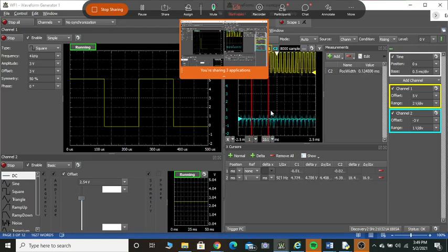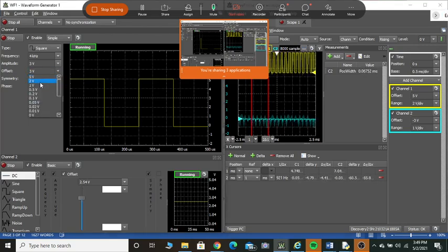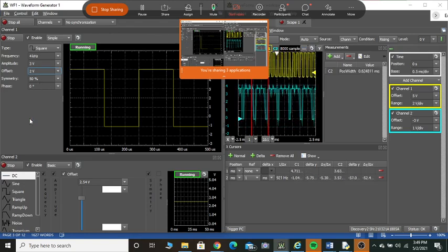Why is the output not coming? Output is not coming because the spike that was going down, because this trigger signal is not going below half of this. Half of it, it's not going below 1.7 volt. If you want to get it, either you can reduce the offset voltage to 2 volt. You can see you're getting it, or you can increase the reference voltage. Correct? Okay. Shall we move on to next now?